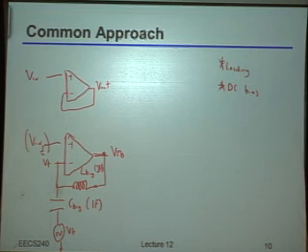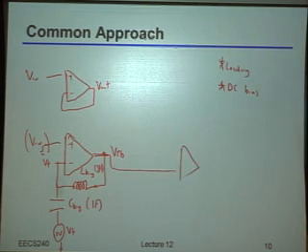But we also said that the loading was messed up. So how do I fix that? What should I do to try and fix the loading now? And again, this is totally a SPICE hack. So how can I mimic the loading to try and make it about right? Yeah, exactly. So I basically take another thing like this and put that same amplifier over there. Now, by the way, when you said a copy of that, did you mean a copy of just the amplifier, a copy of the whole bias T, or what exactly did you mean?